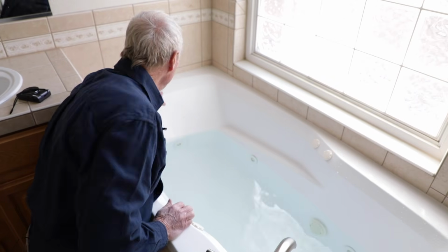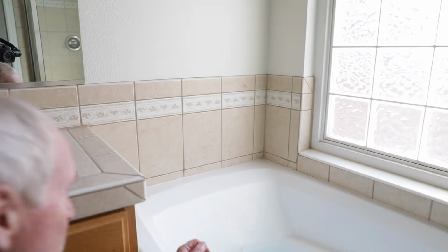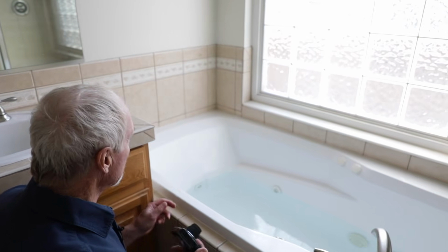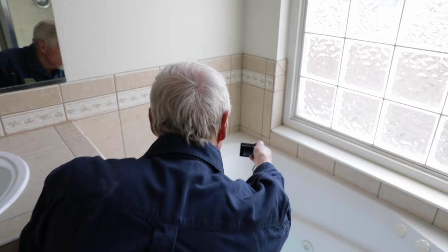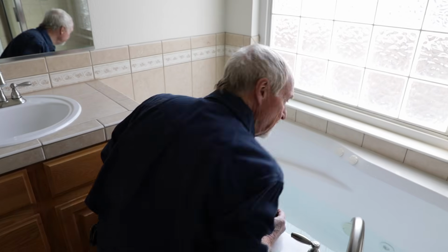Could be that over time the weight of the tub has pulled it, or keep in mind that the material the tub is made out of is different than the tile, and you have differences in thermal expansion and contraction between the two materials. But I don't think that's any big indication of a problem. I just think we need a caulking repair done there. And I will, of course, take my photo showing the caulking repair is needed there.